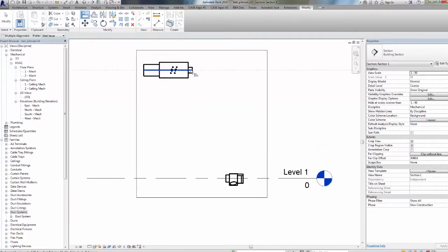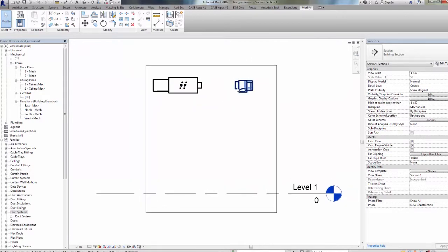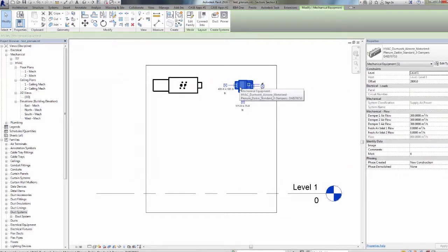So we are now aligning the plenum with the indoor unit. Here it is actually easier, since the placing plan of the plenum is exactly the neck center plan, as it is in the indoor unit. So the placing reference plan coincides with the air supplying connector.